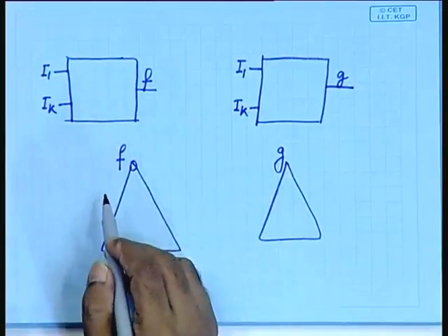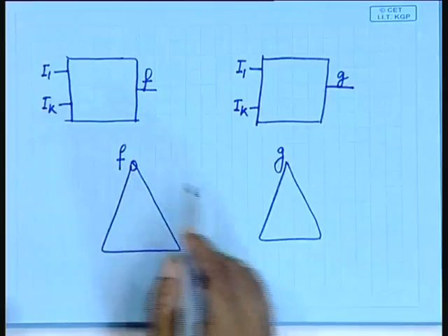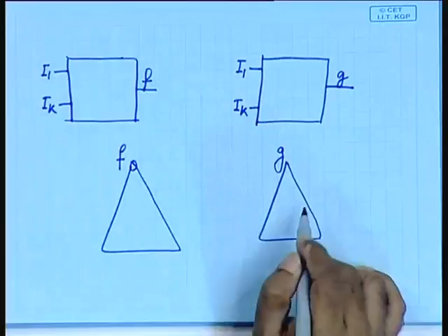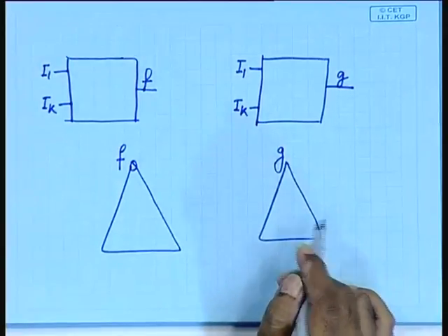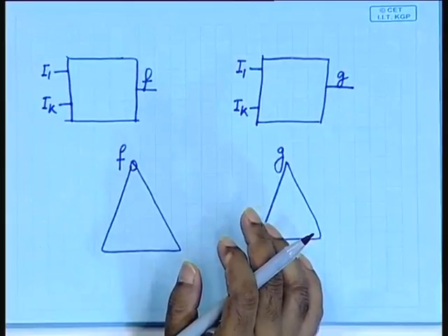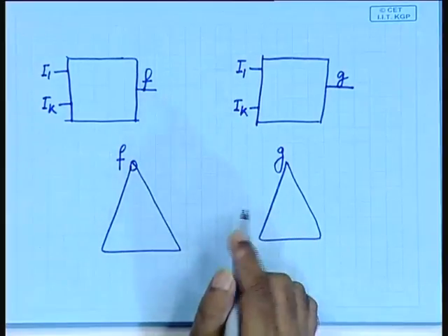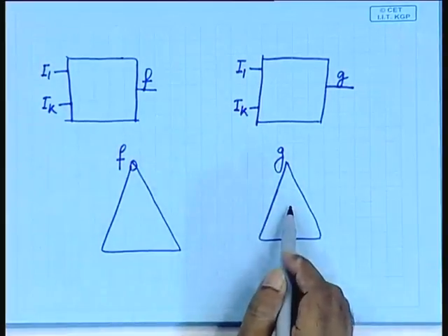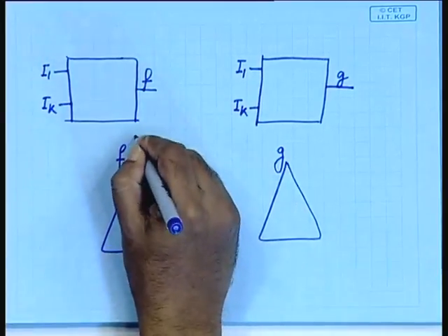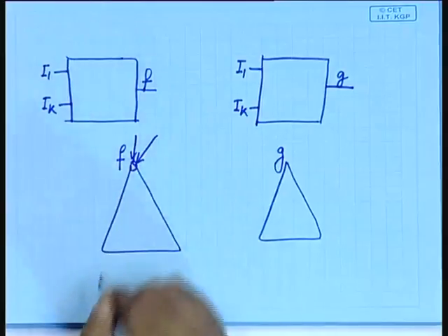Now, suppose they are using the same structure. Now, suppose you think of this as the same BDD. See, the BDDs are going to share it, all common functions will be shared, right. So, when you reduce these two BDDs together, what will happen? If they are the same function, f and g are going to point to the same node.